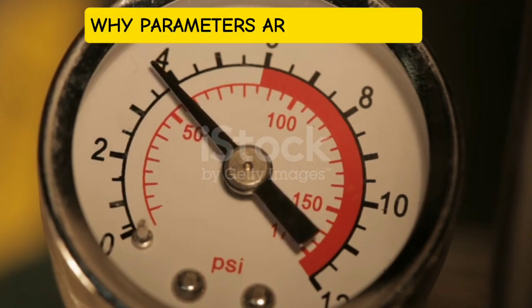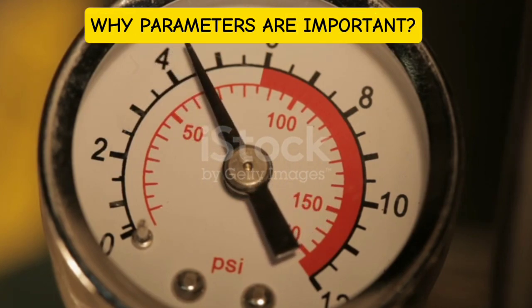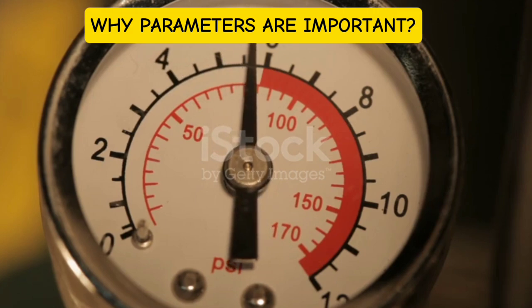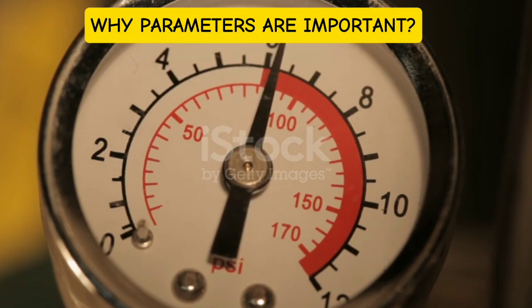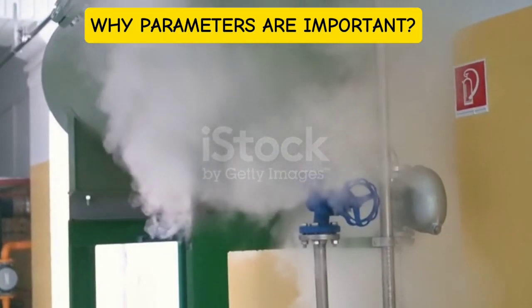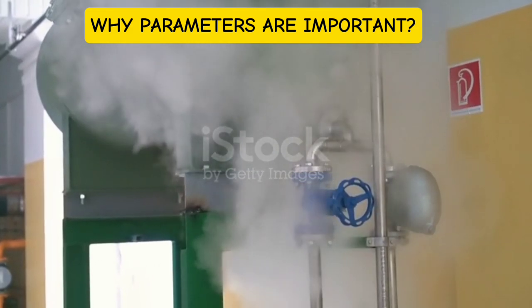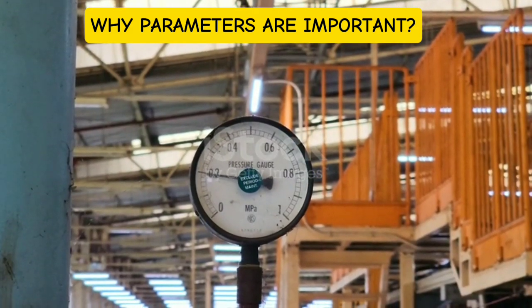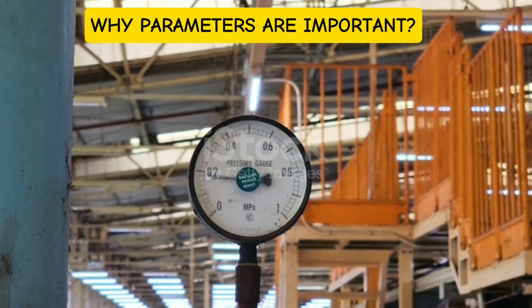Why are parameters important in a HAZOP study? Let's review why they are important. Parameters are the backbone of a HAZOP study. Why? Because deviations in these parameters, such as a sudden spike in temperature or an unexpected drop in pressure, are often the first indicator of a potential hazard.